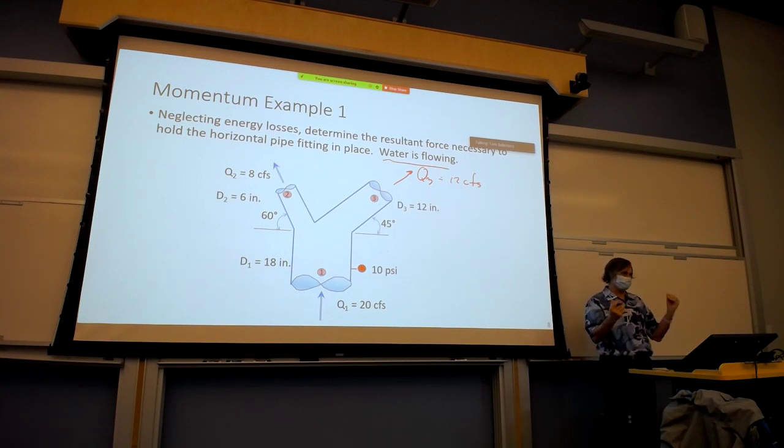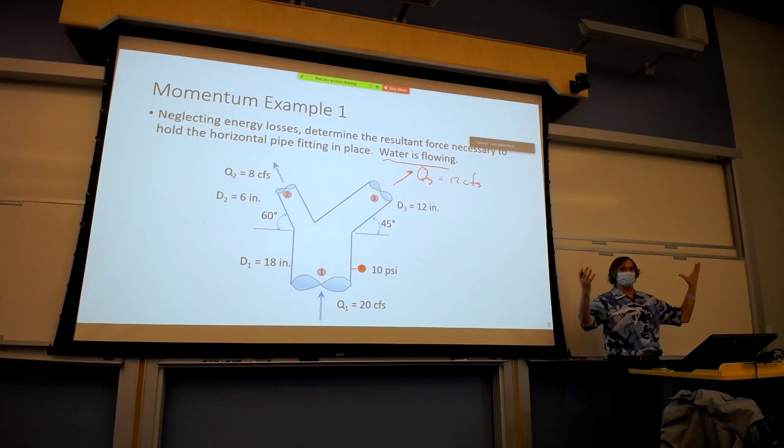Continuity must be met. The sum of the inflows is equal to the sum of the outflows, and there is no dV/dt, change in volume with time, because this system's already full. If this was a sewer that was not already full, then yes, you can actually store water in there temporarily. It's steady state now.